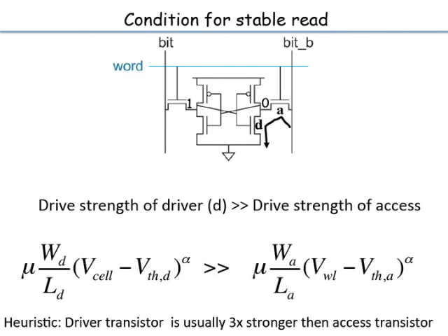So absolutely, because one thing you can say is that, look, I'll make my D very large, I'll be very safe, but you can't make the driver transistor too large, because it increases the area of the cell. Now, of course, the benefit of making things large is you also have large drive currents, so speed can become bigger.